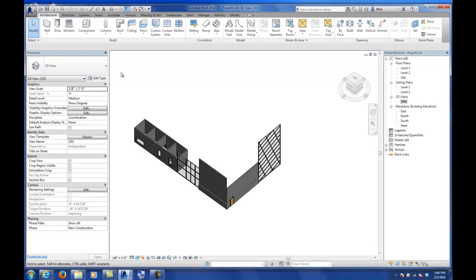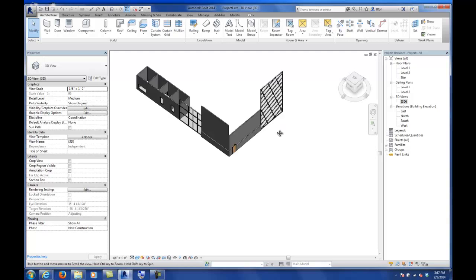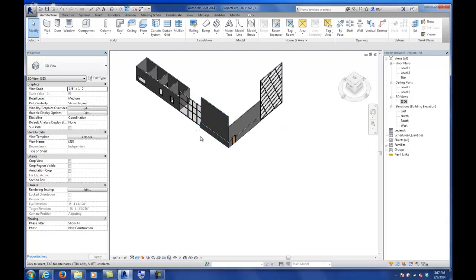And when you see these tools so far, you kind of get stuck in that you can only be in this particular environment of only having walls straight up and down. We can actually model walls to another component, and if you click on the down arrow under walls, you notice there's this option here to model by wall face.